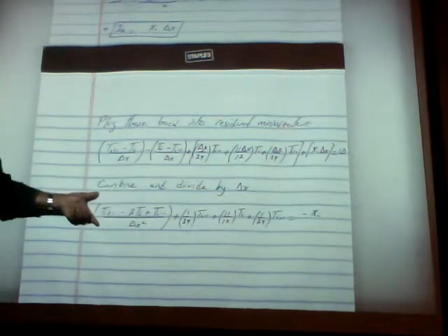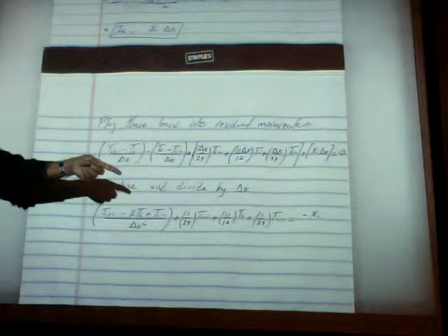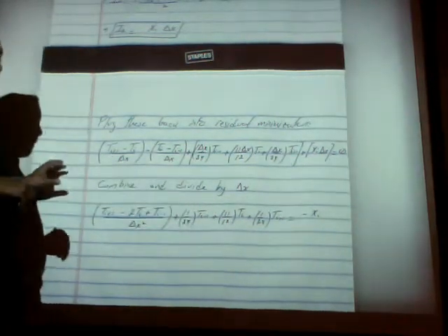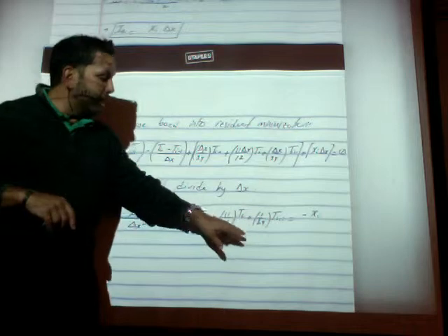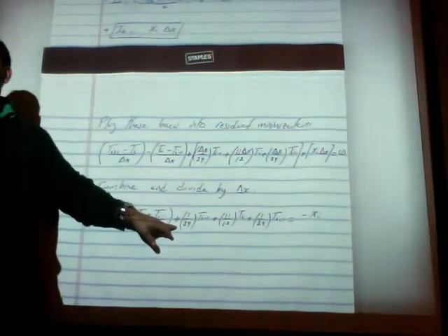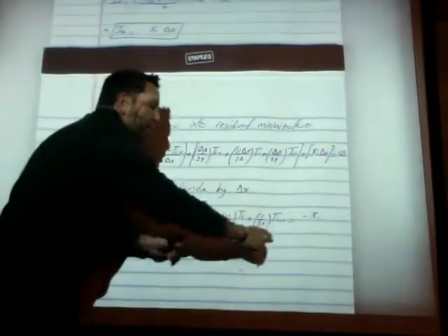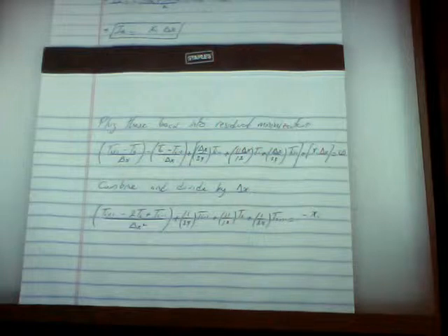We end up with the same exact approximation, but T at node I is no longer just T at node I. That temperature, when integrated, has portions of the temperature to the left and portions of the temperature to the right. Small portion though. It's 1/24 of it and 1/24 of this one. And this is what the integration does. This little thing here is the only difference between finite differencing and what we got, which is finite volumes. Okay? So this is exactly equivalent.